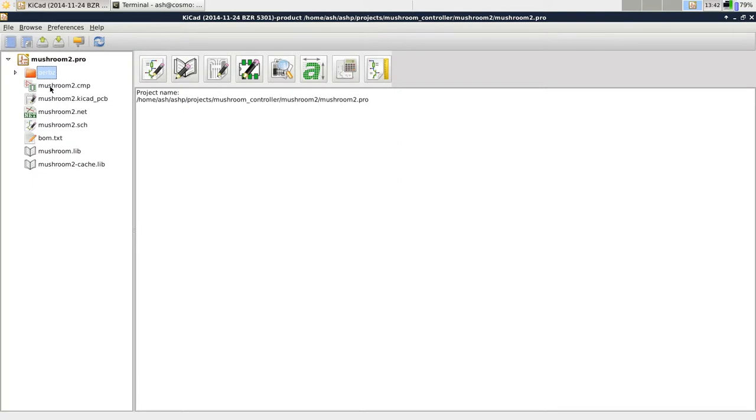Okay, I realise I'm going a bit backwards here, but just bear with me. Now, this one, the SCH file, that's the schematic. The schematic is a logical layout of your PCB, diagrammatically represented. There's a program called eeschema, and that's the program that you use to generate a schematic. That's the first thing you start with.